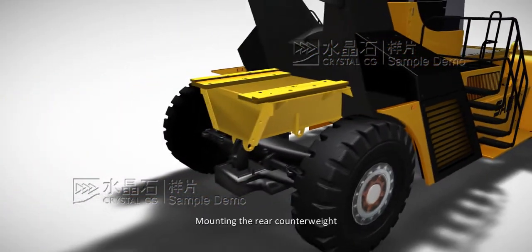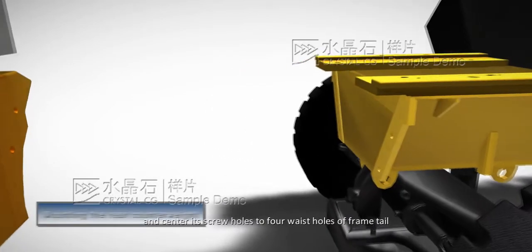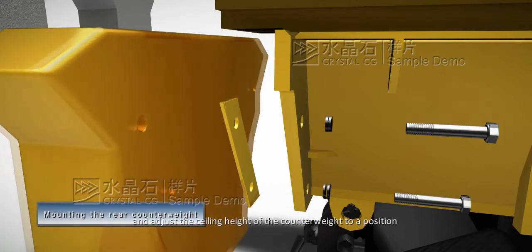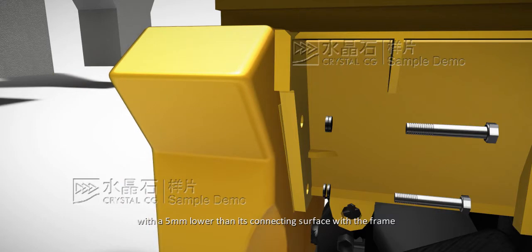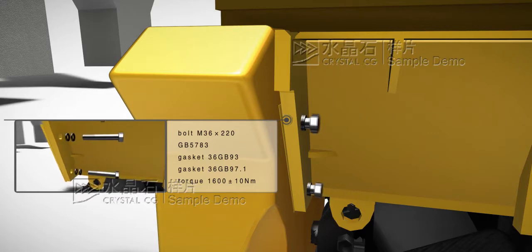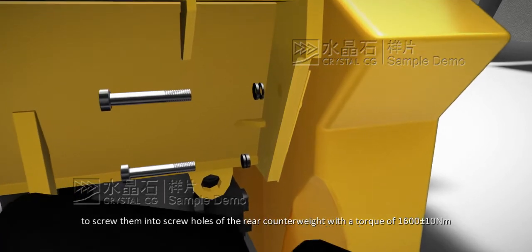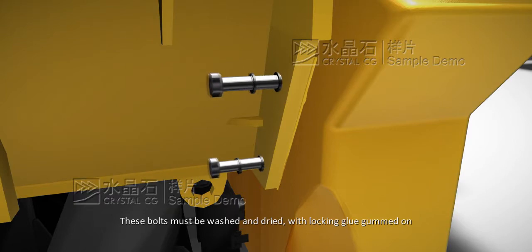Mounting the rear counterweight. Lift the rear counterweight with a crane and center its screw holes to the 4 waist holes of the frame tail. Adjust the height of the counterweight to position, with a 5 mm gap lower than its connecting surface with the frame. Put gaskets onto bolts, and move them through the rear part of the frame body to screw them into the screw holes of the rear counterweight, with a torque of 1600 plus or minus 10 Nm. These bolts must be washed and dried with locking glue.